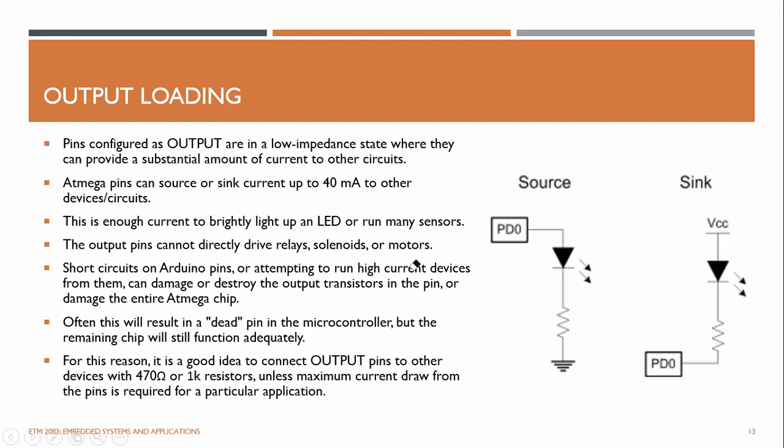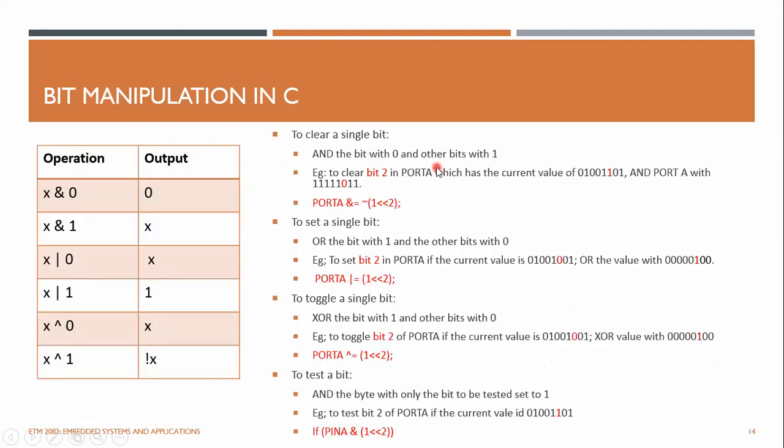So be careful when you're driving from the output pin. Don't allow it to short circuit or drive any current more than 40 milliamps, as that could potentially kill the pin. All right.